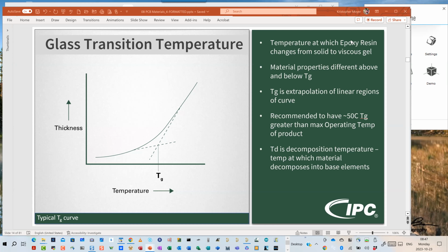But if you build a board with commercial off-the-shelf parts for commercial temperature range, 70 degrees C or 85 degrees C, and you start taking those parts up to 100, 125, 150 degrees C, yeah, they're going to be affected. But in theory, your board should never get there unless you're military. And if you're military, you're selecting parts that also are rated to those kind of temperatures and so on. So it all depends on the parts you put on your board, Mattia.